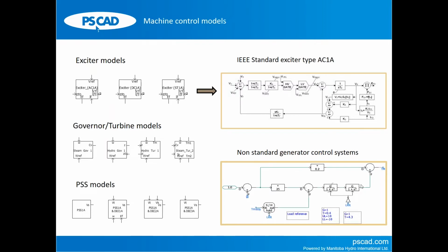Connecting control blocks is simple. You look at your block diagram and just connect the blocks, but it takes a little bit of effort to back initialize, or make sure that the control blocks get initialized to an expected initial condition.